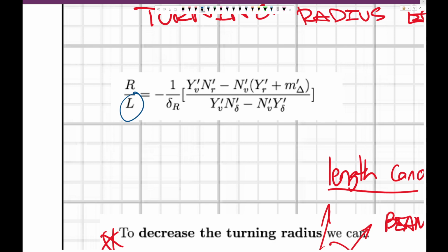So yeah, the difference between a 20-foot canoe and an 18.5-foot canoe is pretty big. So I would say chopping your canoe is probably the most efficient way to decrease your turning radius. And also, this is your inertial effects with your mass. If you decrease the weight of your canoe, it can not only turn faster, but it can also accelerate faster and change direction faster. So if you made a lighter canoe and if you made your canoe shorter, those are also going to help.